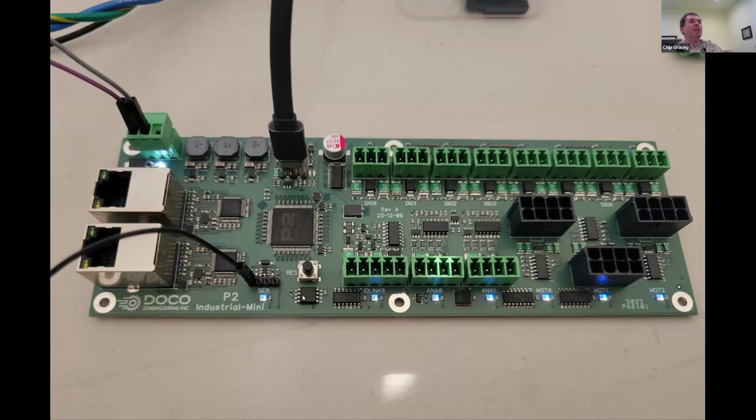And then we used a big chain of these RGB LEDs. They're like WS2812s, but it's some other part. I can't remember the name, but they're 1.8 by 1.8 millimeters. You send them a serial stream, and they all initialize when you finally hold low for a while. It's a one wire deal. So it sends out to all those and then updates them. And I've been working on all the software for this.